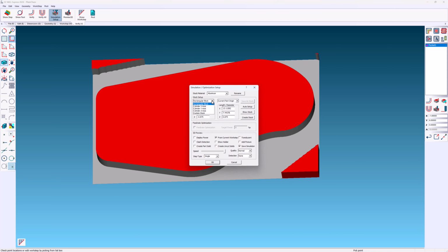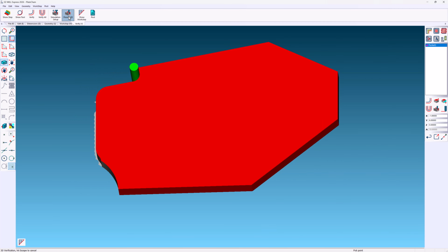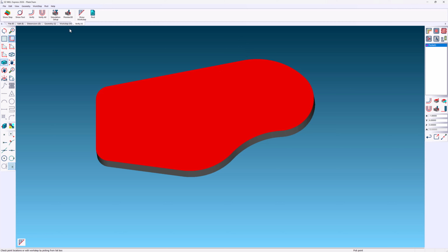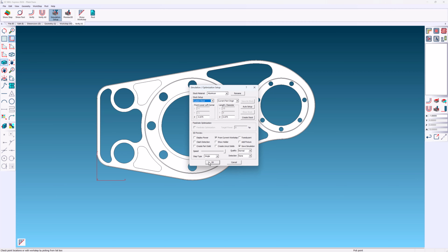As you might guess, we will choose custom stock in our stock setup. Our toolpath is absolutely efficient with no wasted paths. You'll find more options in simulation setup. Outside of World on Model, we can choose to create square stock here, round, or custom. The behavior is similar to World on Model with our auto setup and create stock, but we can show the stock taking a glimpse at the results.